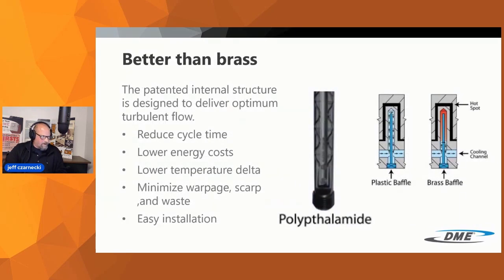DME a little while ago did introduce the plastic baffle. We got a patented design here. We have some features that help provide consistent tubular flow as these waters reach standing cores and standing cavities. This will definitely help you reduce your cycle time, reduce energy cost, maintain a lower temperature delta, eliminate scraps, and it's also very easy to install.